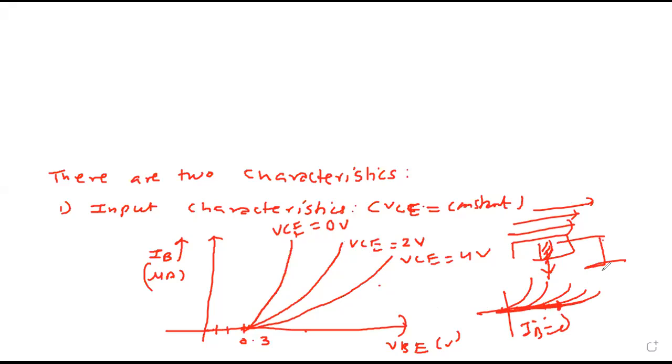As you increase this collector emitter voltage, more charges will enter here and few will enter here. A stage may come where no charge is entering in base region, and we get all current flowing through collector and emitter only. So draw this graph.